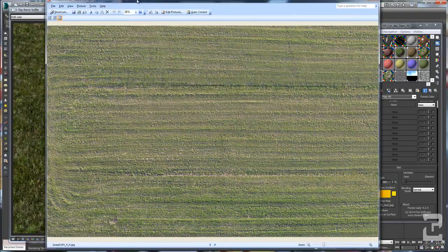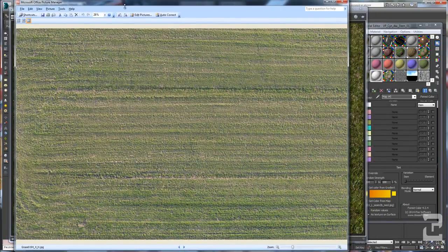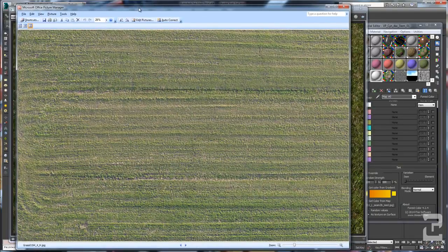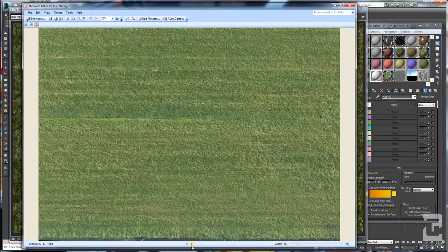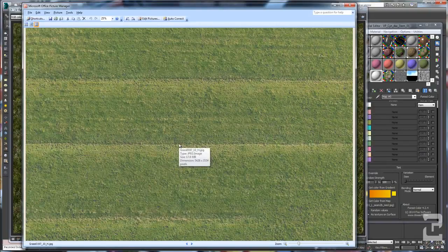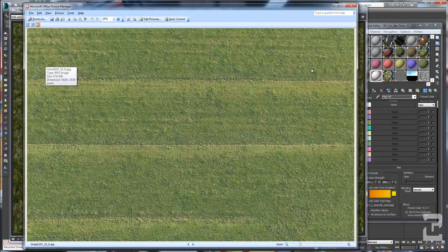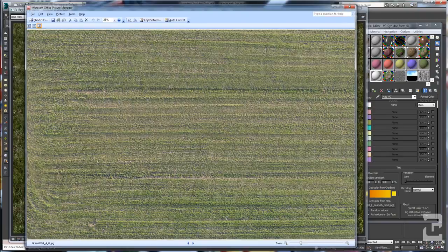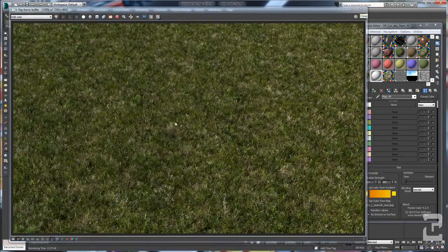And the next thing is how we can use the forest color to create grass. A couple of months ago we had a project where the client asked for grass like this for the villas. It's going to be really painful when your client asks for this kind of grass and needs a close camera shot. You won't be able to get a very realistic result with a displacement mode. We managed to get this kind of texture because we used the forest color. So let's close this rendering.